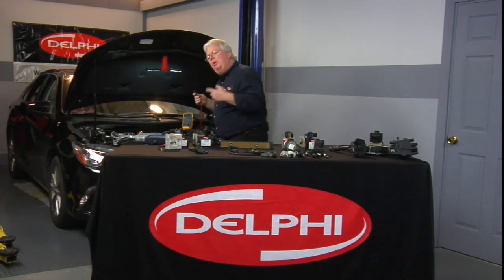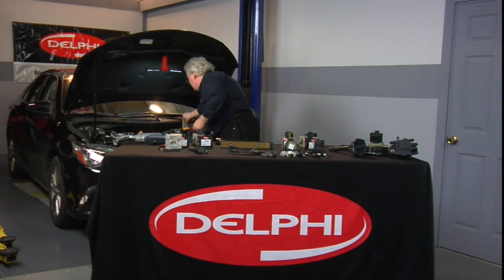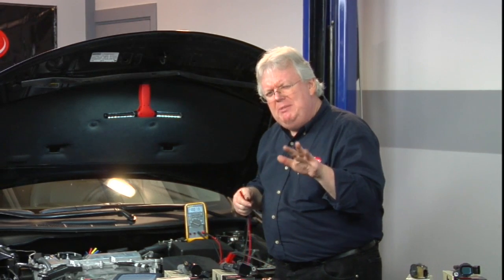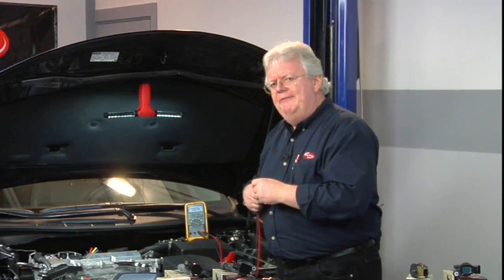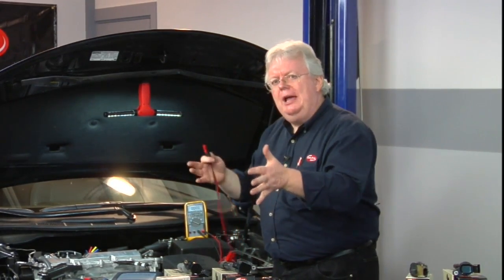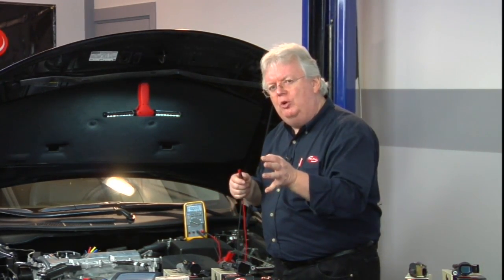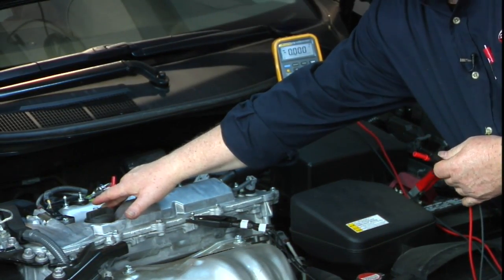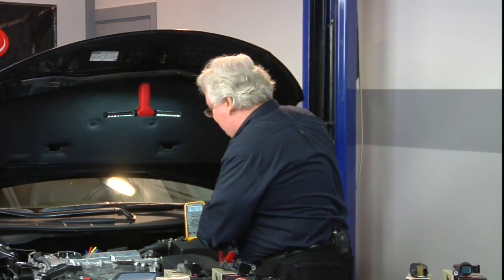And I'm just going to go ahead between the two on DC volts. If I don't see a good 12, 13 volts, with my Midtronics battery charger on here, a little battery tender to keep this thing up, I should see maybe 13 and a half volts. If I don't see that, then I'm going to look for a voltage drop on either the power or the ground. I'll check them both. But if I've got a good 13 volts with presumably a load of the little module, not a lot of load right now, that's going to be a first step here.